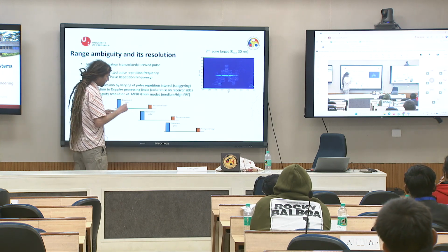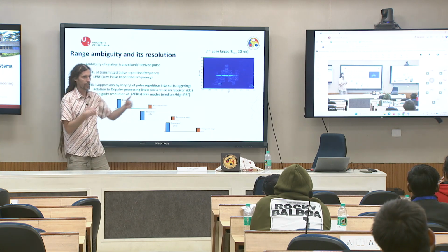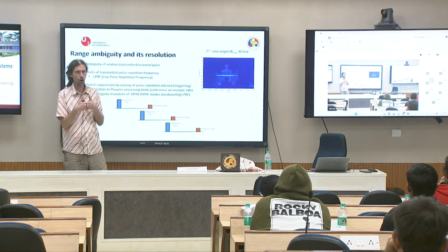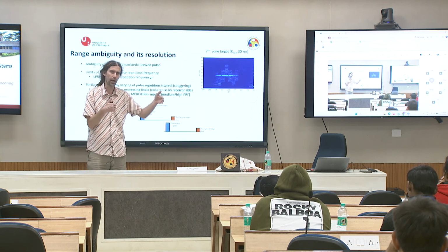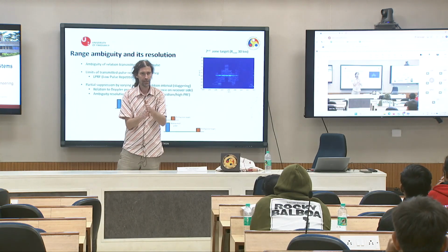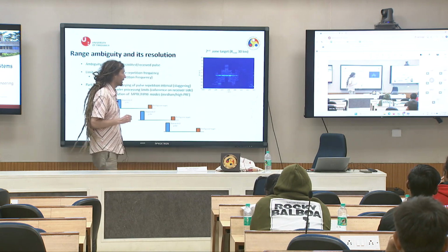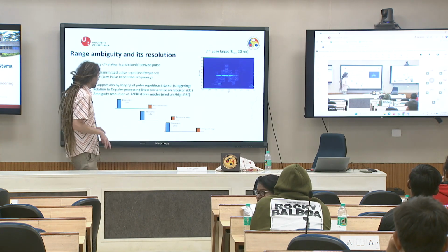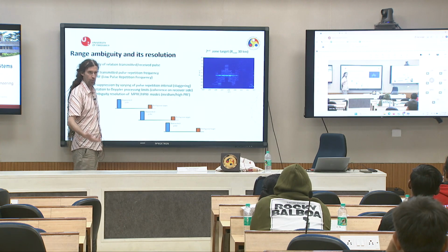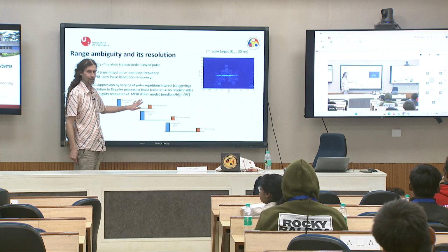There I need to be extremely careful because I can't listen for an answer for a very long time, only up to some maximal time delay. Why? Because then I start the transmission of a new pulse, if you get my point. And then again. In the tutorial I will show you how to compute the ambiguity range and how to deal with it. Is it clear? Can I continue?